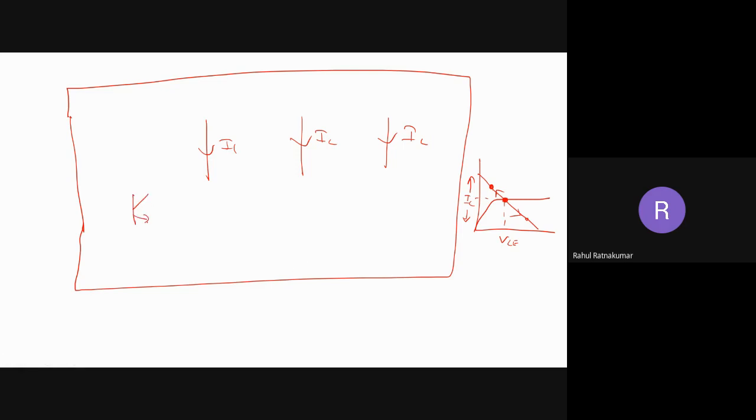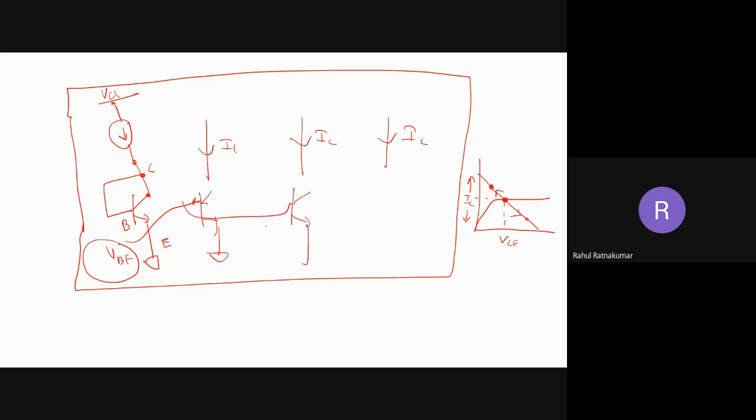So basically, a current mirror is nothing but a BJT that is diode connected. What is diode connected? With the collector and base shorted together, it is called a diode connected BJT. And to the collector side, we connect a current source. This base emitter voltage, if I give it to different transistors, I can short circuit it to all the different transistors in the circuit, and I'll get the same current IC in all of their branches.